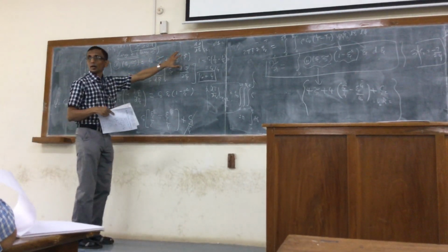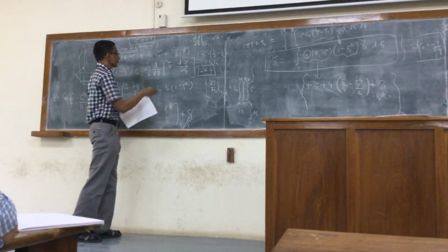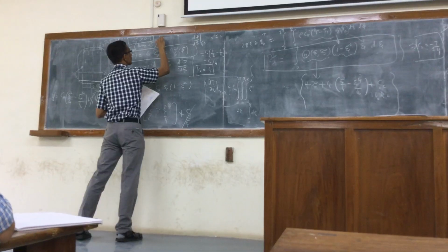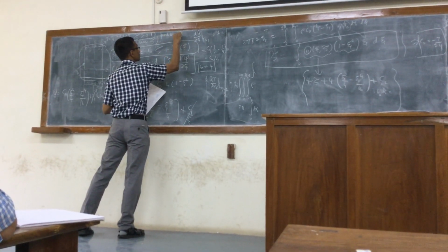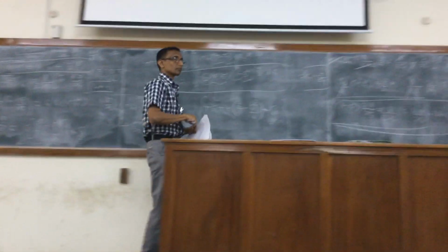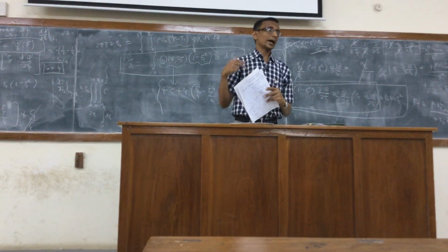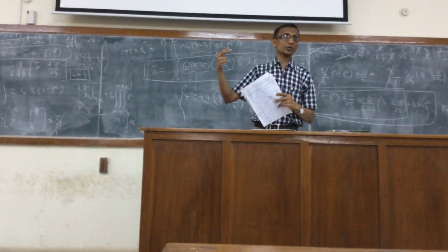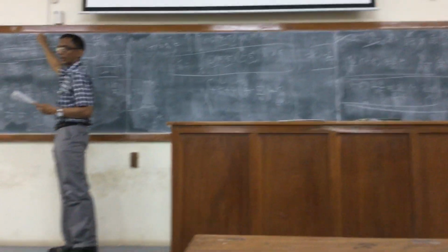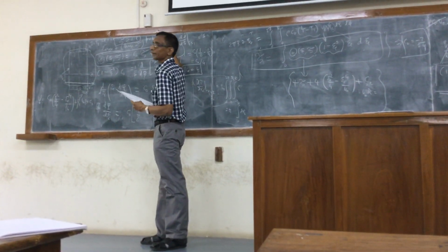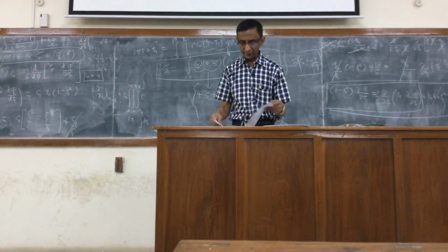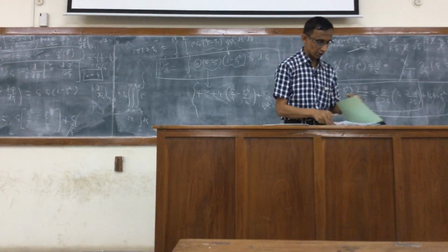So this form will work, and we also say that this solution that we have calculated predicts the dimensionless temperature to within 2%. So that gives a measure of the accuracy of the solution with respect to z, how long it should be. So if it is longer than 0.1, then you will get theta to predict within 2%. So that's a good solution, right? We will see later on how to get the full solution and what are its implications.